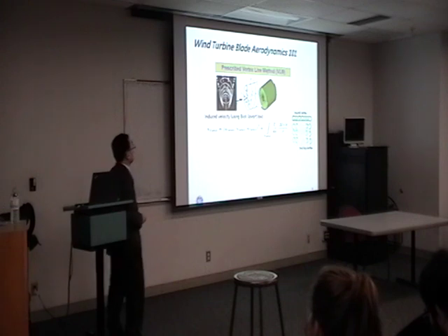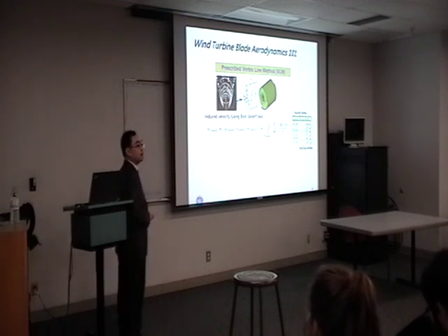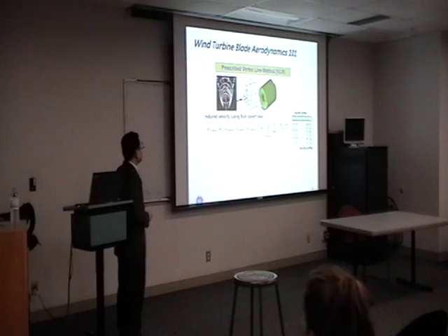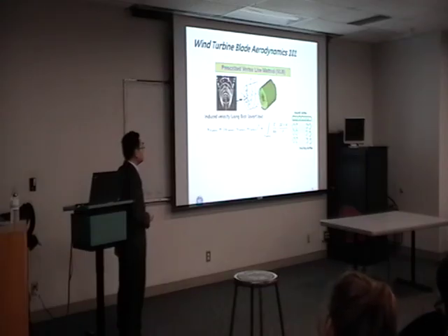There is another, more accurate method for aerodynamics, which is the vortex line method. This is called the VLM. The vortex flow that comes from the rotating blades induces velocity on the rotor plane. This induced velocity can be calculated by the standard Biot-Savart law. Here, gamma is the vortex strength, or circulation.